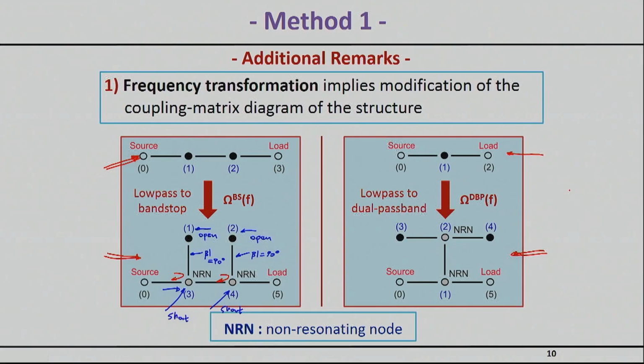So the best way to essentially understand those coupling diagrams is basically with exactly what I gave you here. By essentially thinking of what the response of this resonator is, how it's reflected from the coupling sections, and basically go from there. Similarly, you can interpret the coupling diagram here. Here, basically, each one of these resonators will undergo essentially 2 reflections until it basically goes to the signal path, right? So essentially, this will implement a passband response.